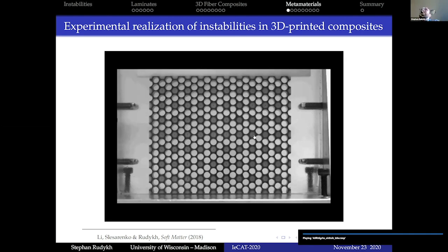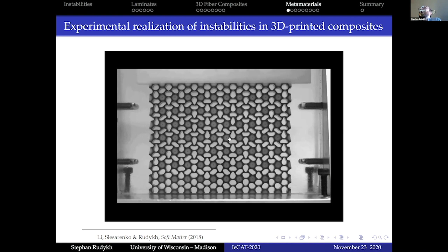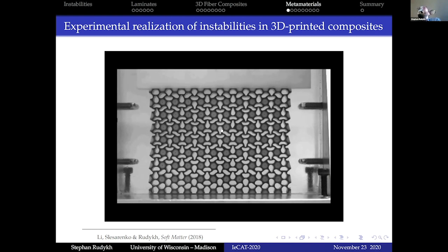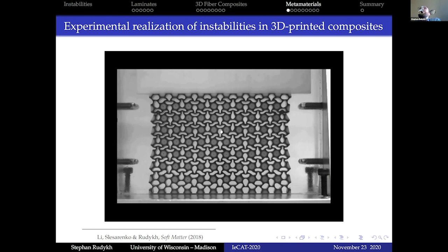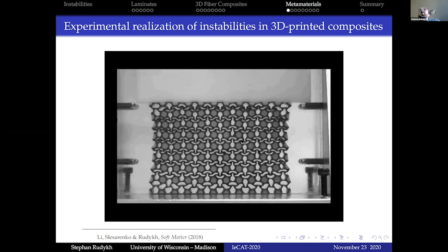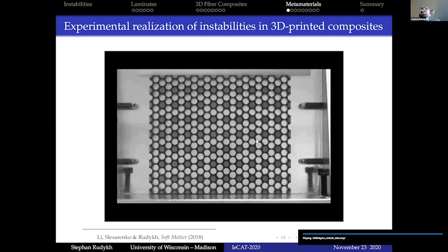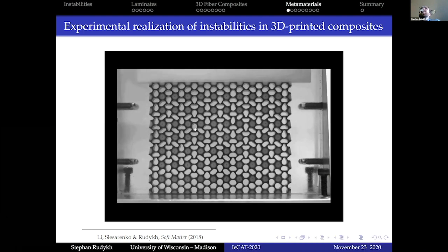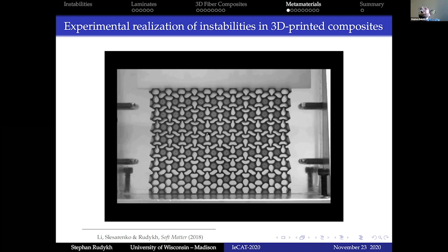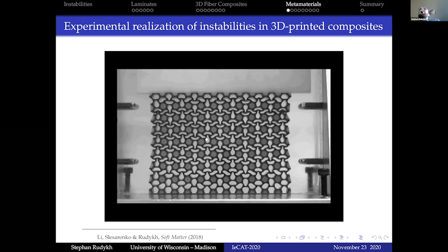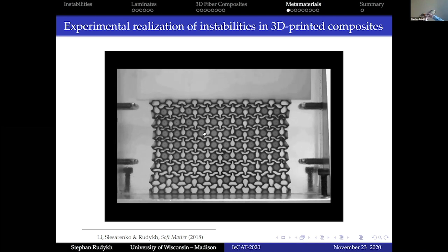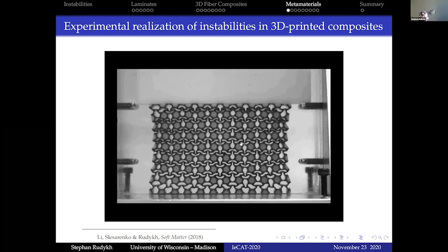All right, I need to be quick here, I think. The white part is the voids that collapse. And basically, if we were able to go to the beginning of the video, you would see that at the beginning there is some chirality-like structure that forms, and then you continue to break that. By positioning these stiff inclusions, you can regulate what will happen here.